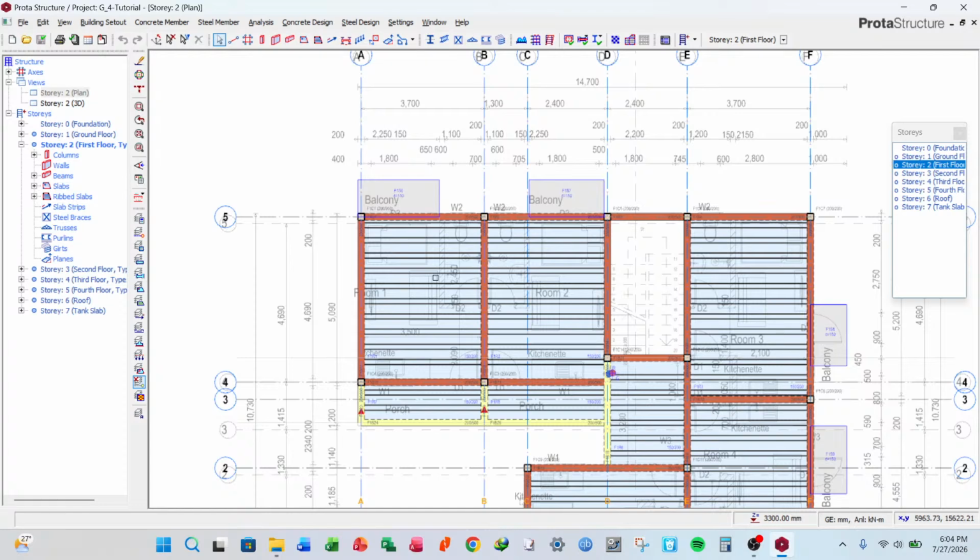why we started with slabs is that we do not want to design a beam and then later come back and find out that our slabs are insufficient and that we have to make adjustments to the geometry of the slabs. This will have an effect on the loading imposed on the beams. Hence it will affect the beams, which in turn affect the columns, which in turn affect the foundation. So we shall design from up to down. Okay, so top to bottom.